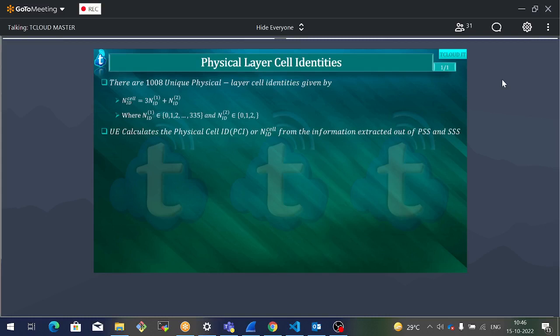Now let us summarize. Mobile equipment can easily detect this synchronization block because there are some special symbols placed, which are specially modulated symbols that work on a 0 degrees, 180 degrees mechanism, which no other channels would use. So they are easily detectable when you are scanning through the frequency and decoding a 7.2 megahertz subband every time. If you take 30 megahertz as your operating band.